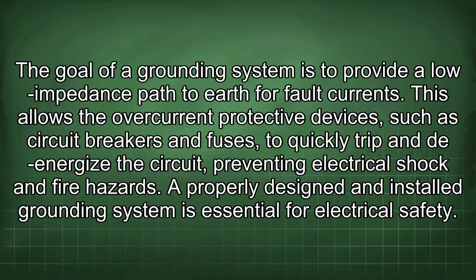This allows the overcurrent protective devices, such as circuit breakers and fuses, to quickly trip and de-energize the circuit, preventing electrical shock and fire hazards. A properly designed and installed grounding system is essential for electrical safety.